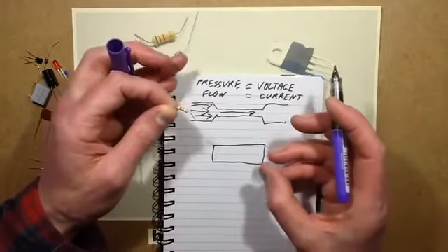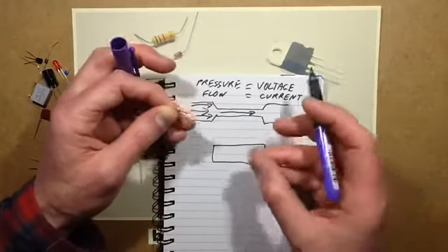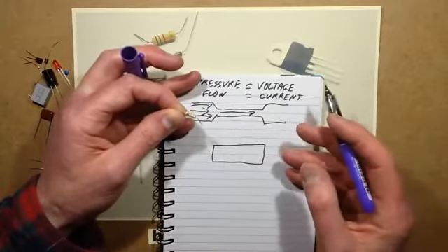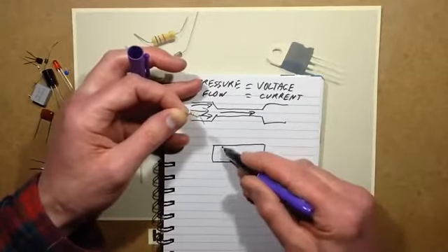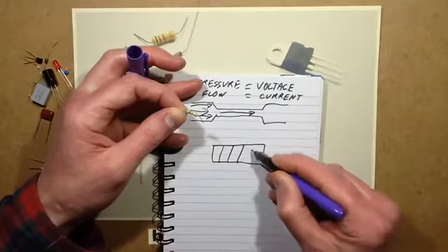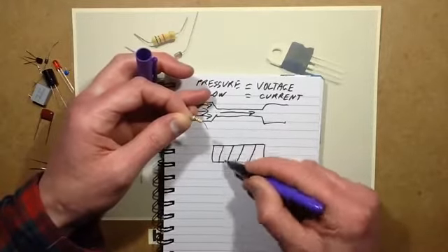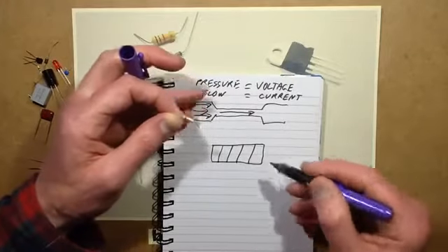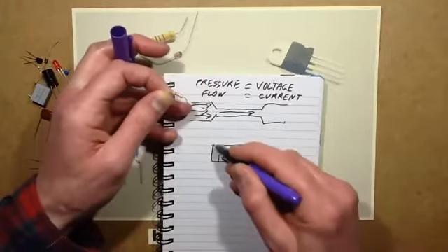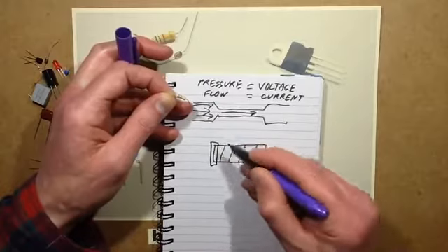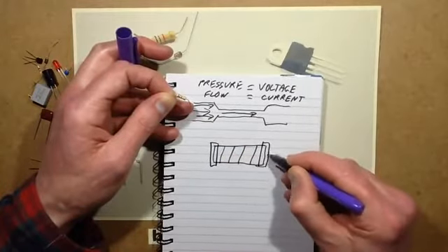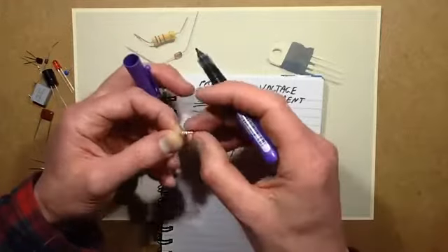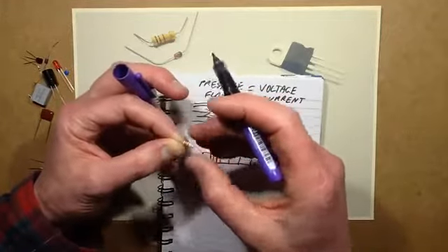And the thicker the carbon coating on it and the type of the composition they're putting on it, the more conductive it will be. But then they can fine-tune that. They actually cut a spiral round it, and that creates a long, thin path of the carbon, and that increases the value of the resistance. And once they've done that, they put a metal cap in the end with the leads coming off, and they dip it in a sort of, I suppose it's a lacquer really.